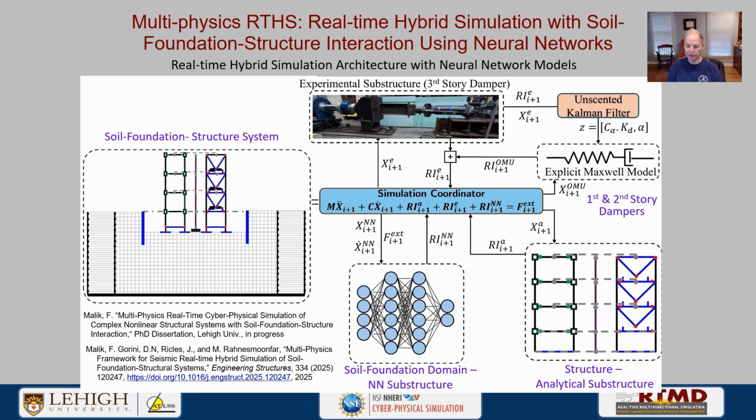The analytical substructure is very similar as before. We're going to have finite element models in which we have force-based fiber elements, panel zones, and lean-on columns for geometric stiffness.